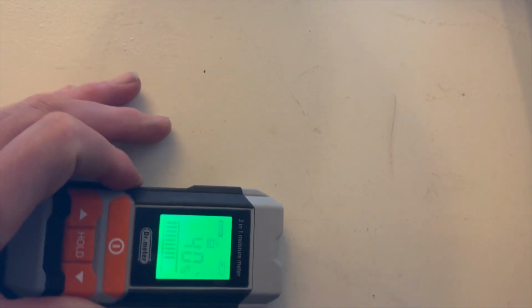But what I was going to say is that where you've got mould, you often have condensation at the base of the walls, and this is using a damp meter. So it's condensing down at the base. Condensation and mould you'll get in the same environments because of excess vapor and insufficient heat. And insufficient heat behind this radiator, this sofa is going to stop the heat flow. Where's the radiator? There's a radiator here, and there's that one there. So it's getting very poor flow from the radiator, and it's not getting in behind the sofa.